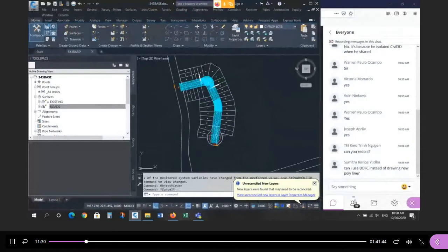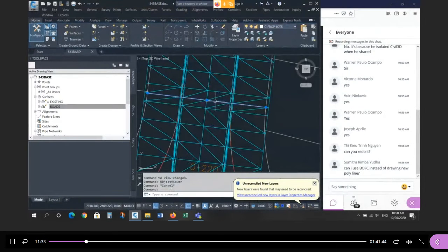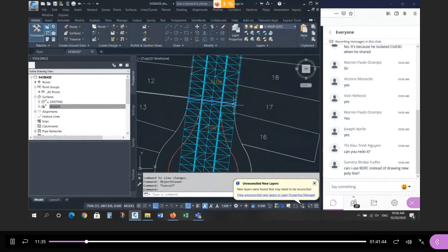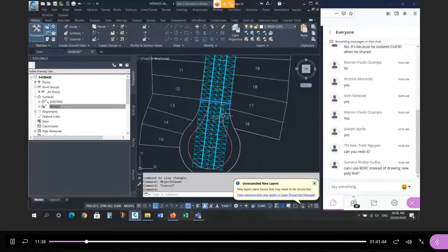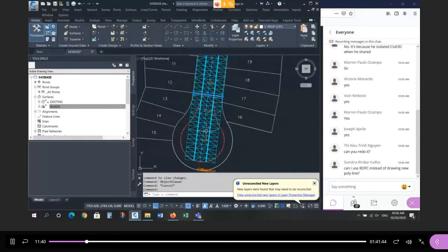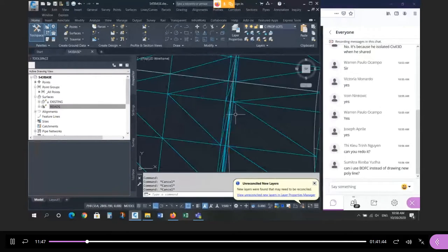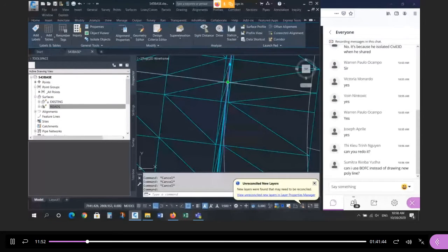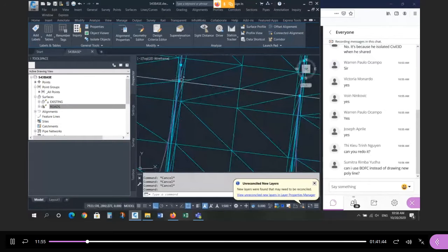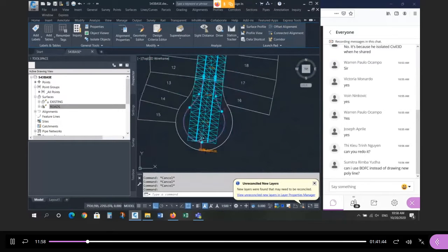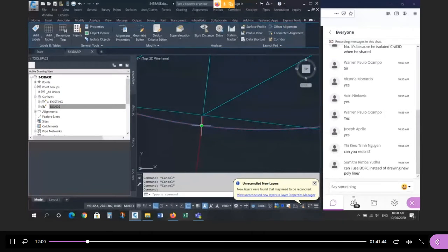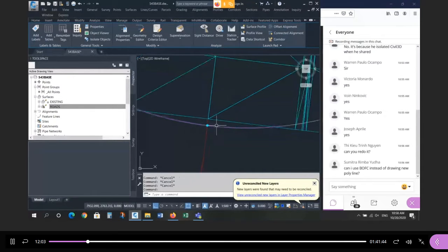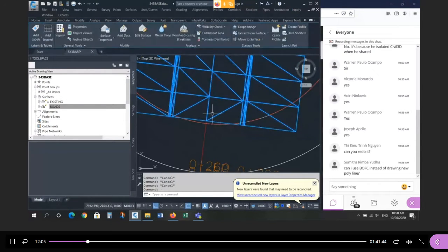Okay, so right now, from this point, this is the last time we have a standard 20-meter right-of-way. Okay, so everything after that going into the bulb is wrong, except for 3 key points. The 3 things that are still okay are the gutter elevation. So if I click on my alignment, the gutter elevation right here is correct. The gutter elevation right here is correct. And the gutter elevation right here is correct. Okay, right here. So what I want to do is make sure that this surface covers that area.